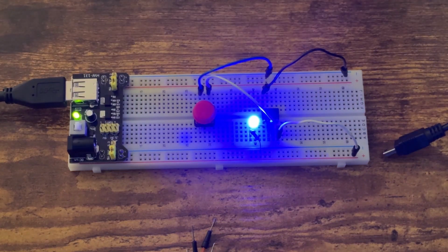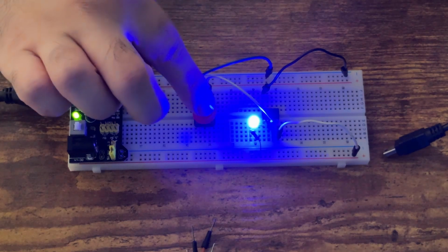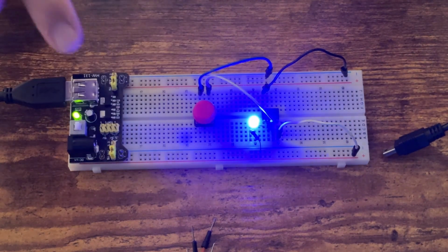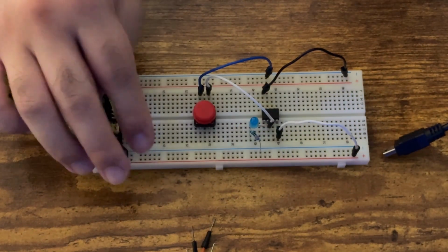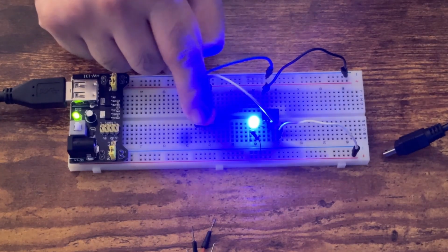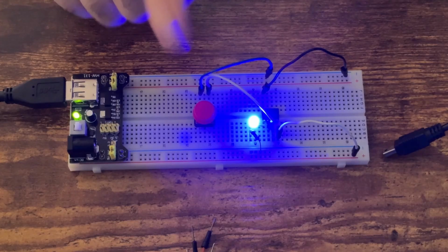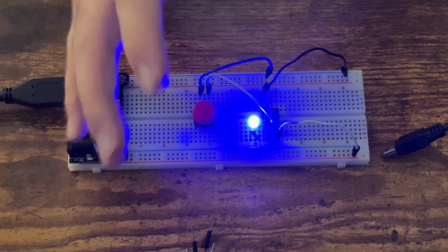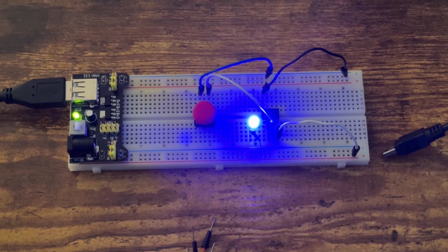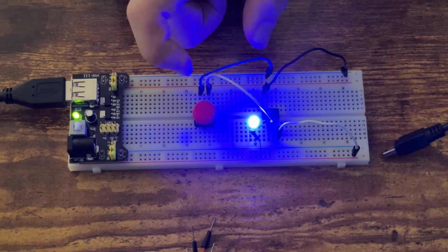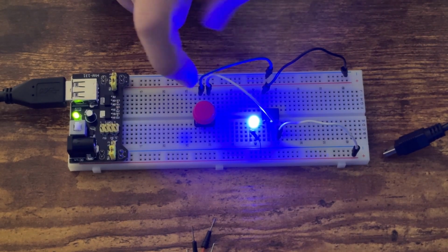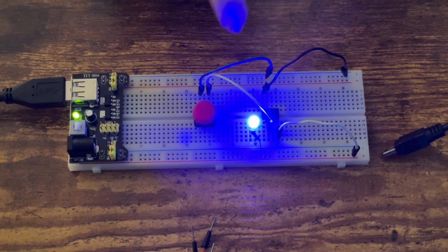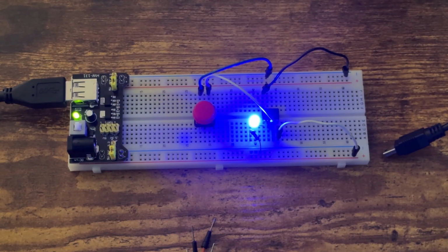Okay, power up. Nothing explodes. LED is not blinking, which is good. If I press a button, all right, it works. And you can actually see even the pull-up works, which is good because you saw it. I pressed the button and it changed state. So this was again pull-up through software. And what we also can do is make pull-up through hardware, which connects a capacitor to the button, I think in parallel with the button, so that it charges up and then gives voltage to the LED, so that we don't have these spikes from the button.